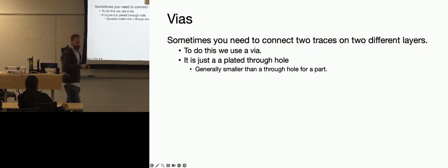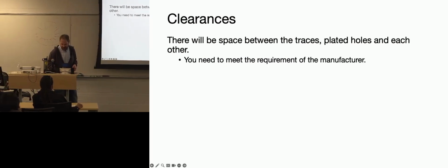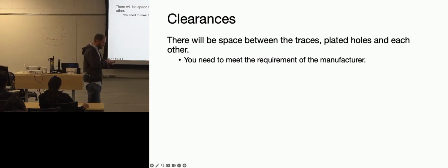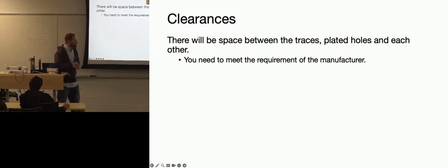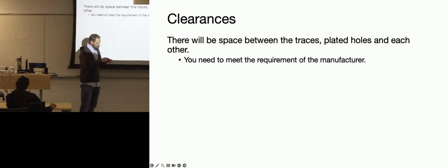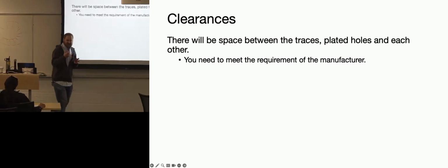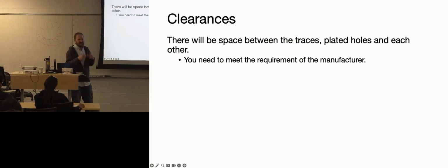We talked a little bit about vias, that's fine. We'll talk about clearance and I'll let you guys go. So clearance, there's probably 3 numbers you need to know for any PCB manufacturer at kind of like the hobby graduate level, even if it's a small startup. And that is, what is the minimum trace size that this process will allow? 6 mils is kind of a non-aggressive but good size. And they're saying, their fabrication techniques will not guarantee that traces less than 6 mils will be manufactured correctly.